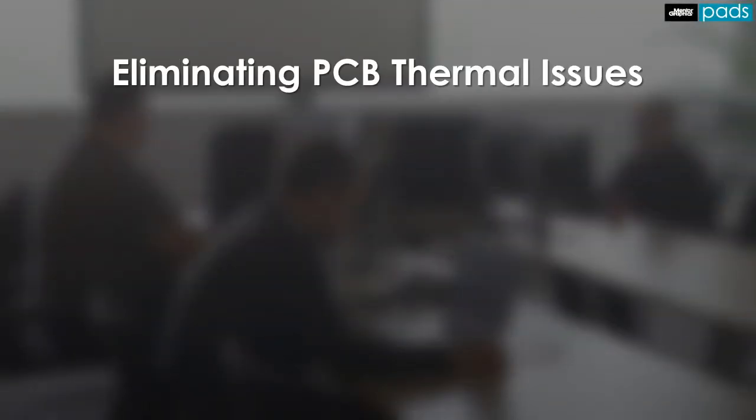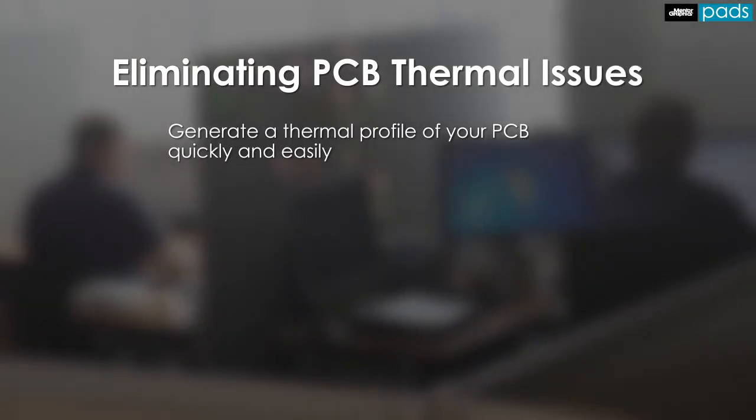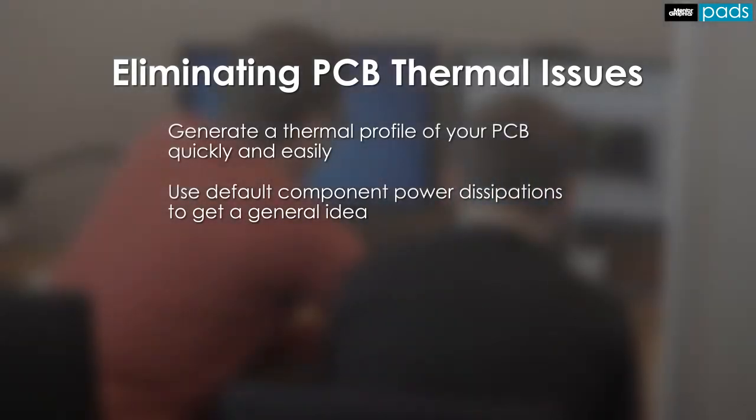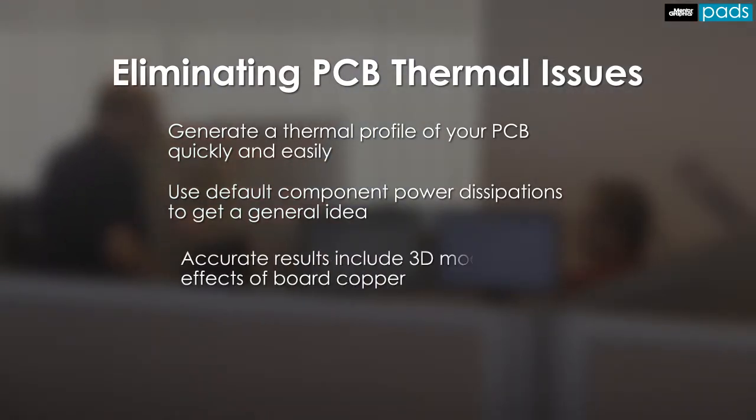Don't guess as to whether or not your board will have thermal issues. Export to HyperLynx Thermal and run a quick simulation to get an idea of what to expect. Default component dissipations do a pretty good job of estimating the thermal profile of the board, and more detailed models can be added at any time for increased accuracy.